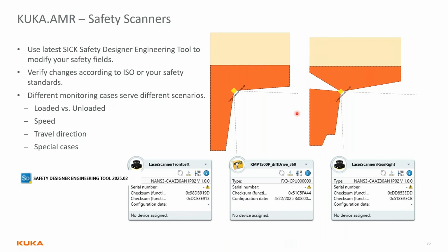Perfect, thank you. A dual one here. How far does the camera look and detect obstacles reliably? And then does it do any obstacle classification distinction between moving or non-moving obstacles? The camera looks up 2,000 millimeters high, so 6.1 foot, and it looks 4 meters ahead. That's what it's looking at, but that doesn't mean that's the obstacle detection range. That's not when it's going to stop.